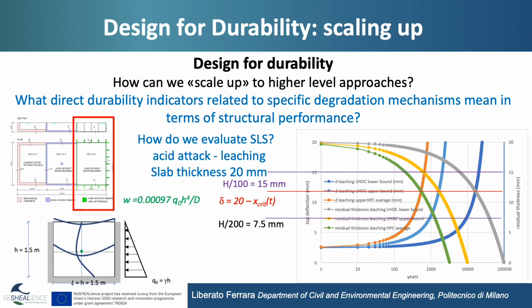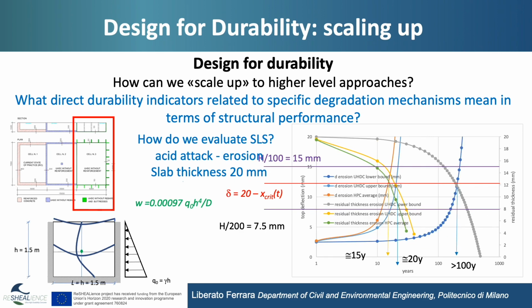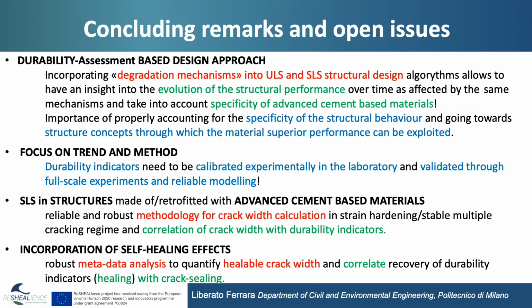So, coming to the conclusions, we have provided a framework to incorporate the degradation mechanisms into ultimate limit state and serviceability limit state design algorithms, which allows us to trace the evolution of the structural performance over time and take into account at the same time the specificity of advanced cement-based materials. Going for specific structural geometries like the slab, we have highlighted also that we need algorithms which take into account the specific structural behavior, so a slab is not a beam,